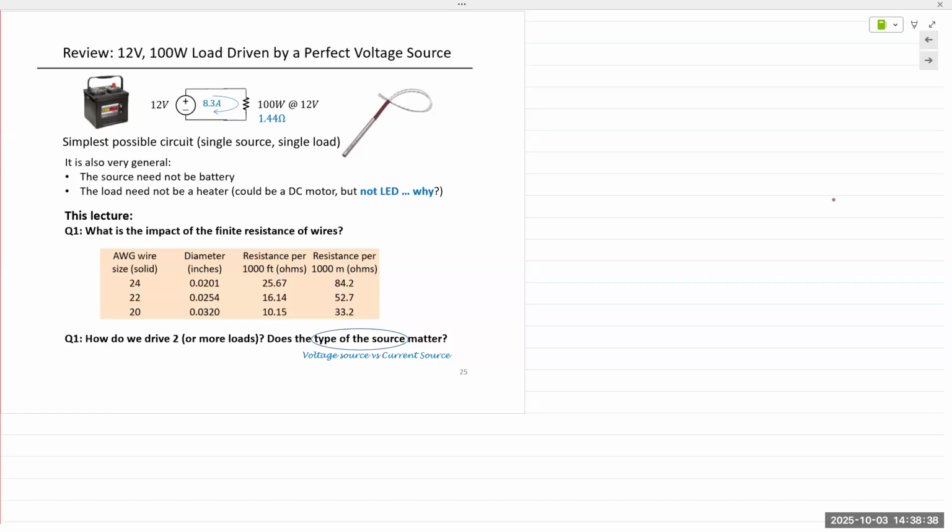So the takeaway here is that if you have a very long wire or cable, it depends on the end application, whether it's going to work or not. So the implication of the length of a wire is that it will have some resistance, but whether the resistance interferes with its purpose depends on the end application. Okay, if all we are trying to do is obtain a little bit of current and voltage from the power outlet, it'll probably work just fine. If you're trying to run something like a heater, then it's probably not going to work.